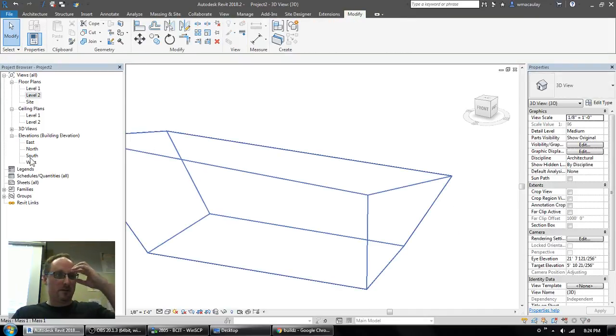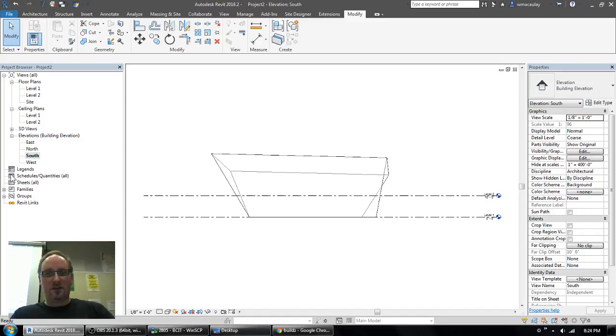And maybe just go to one of your elevations, and you can see how many different levels that you've created already. Now, one of the nice things about the massing tool set is that it can be used early on to do a yield analysis for your building. It'll tell you how much square footage your building is going to be.